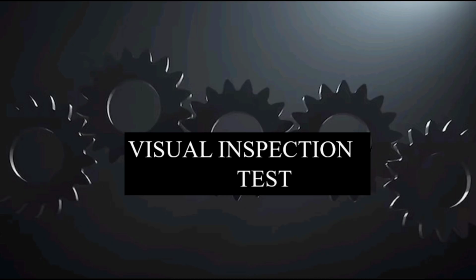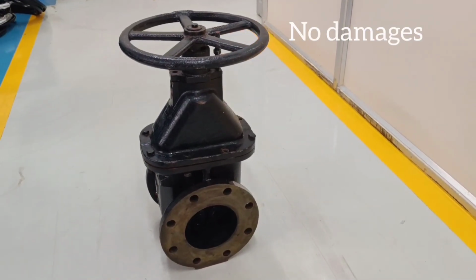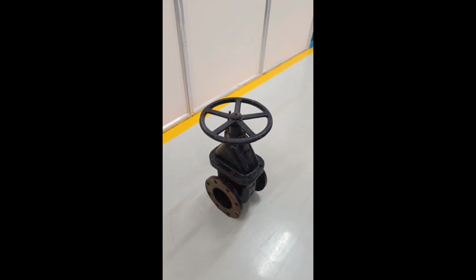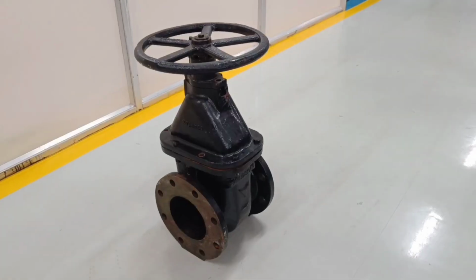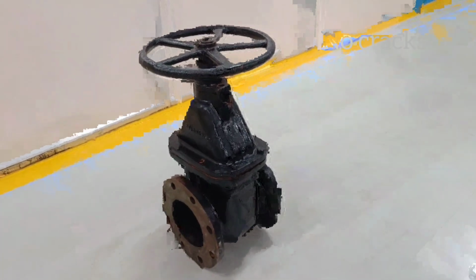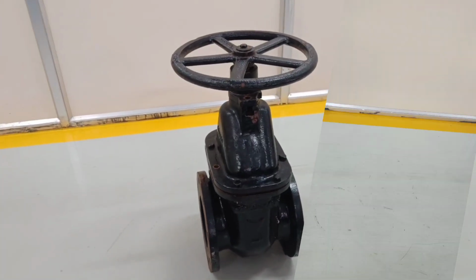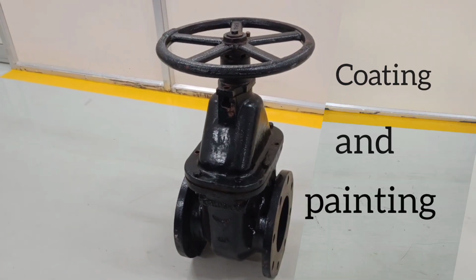Visual inspection test. Visual inspection test ensures there are no damages or leaks in the sluice valve. Inspection of body, bonnet, flange and bolts by ensuring no cracks, corrosion, rust or deformation. Inspection for coating and painting is also done for sluice valve.